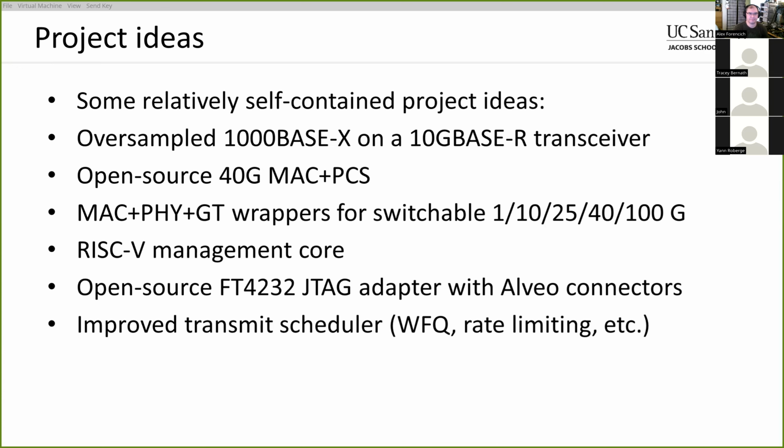Yeah, it seems like the ideal case would be to make it non-mandatory to flash the RISC-V core manually. Have users be allowed to not be aware that a RISC-V is there, but still have the option to do so if need be, but without reflashing the whole thing, right? Definitely, you don't want to make the whole process of flashing a new FPGA board more complicated than it needs to be. You can just flash the bit file, that's the way to go.